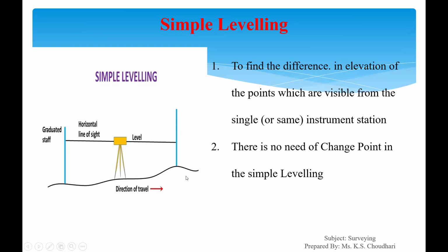This is used to find the difference in elevation of points which are visible from a single, same instrument station. It means in simple leveling, we can easily find the difference in elevation of 2 points which are visible directly without changing the position of the instrument. So there is no need of a change point in simple leveling.